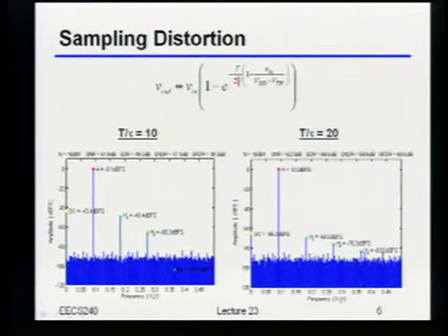Okay? So you can do this in SPICE, but remember, these things that we're going to be looking at are many, many dB down. They're probably 60 to 70 to 80 dB down below the signal that you're interested in. So you really want to build a simple model by yourself, just so you have something to verify against the results you get in SPICE.